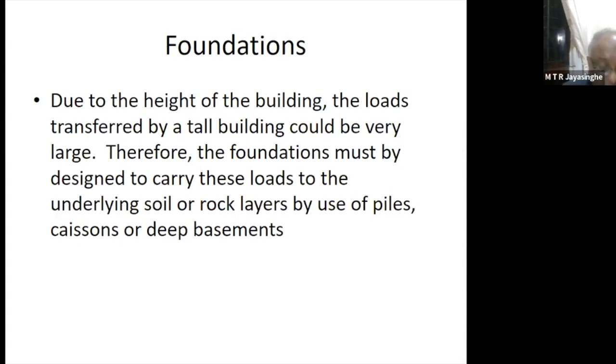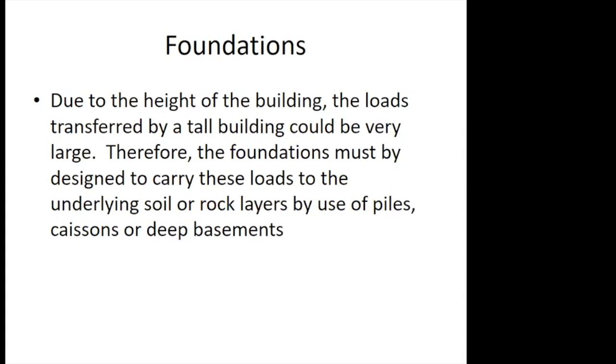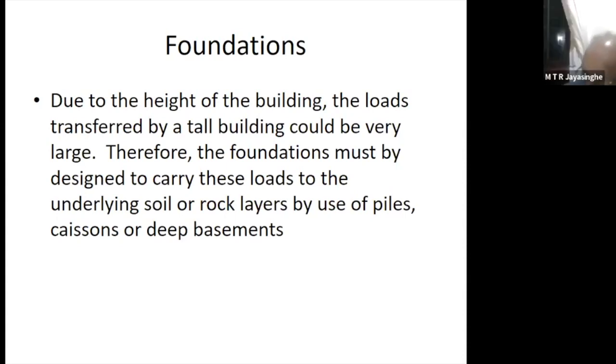On the other hand, you take the piles up to the bedrock, and then the question is, do we need a raft? Answer is no. There's absolutely no need to have a raft, because even if you have a raft, it will not be mobilized. The reason is all the piles are resting on bedrock. The deformation of piles will be limited to 5 millimeters, 6 millimeters. And to mobilize the full capacity of a raft, you need 50 to 60 millimeter settlement or even more, which means you are not going to get the effect of a raft.